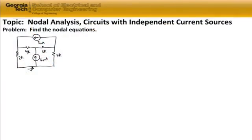The topic of this problem is nodal analysis. In this problem, we're going to work with circuits with independent current sources in them. The problem is to find the nodal equations for the circuit shown. The circuit that we have has two independent current sources in it, a 3 milliamp and a 6 milliamp source. It also has resistors 2K, 4K, 3K, and another 4K on the right-hand side of the circuit.